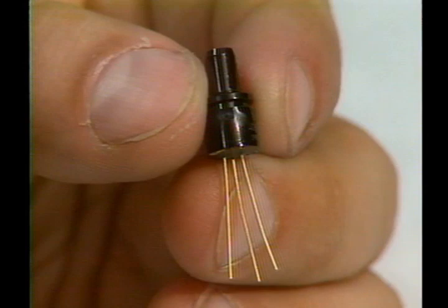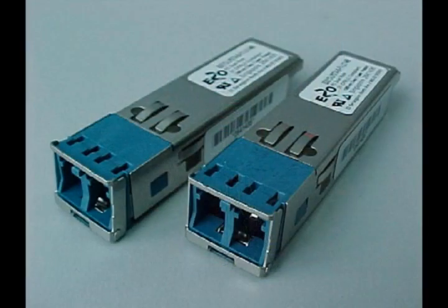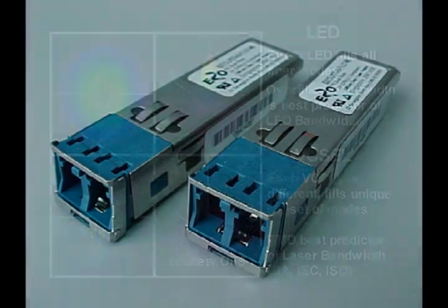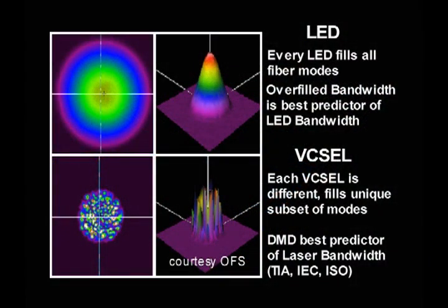The advent of 850 nanometer VCSELs drove two fundamental changes in multimode fiber. The first was with manufacturing performance measurements. For decades, modal dispersion was characterized by overfilled launch bandwidth, a frequency domain measurement of pulse broadening which accurately predicted multimode system performance with LEDs. However, because VCSELs are lasers, they launched a restricted spot size into the core of a multimode fiber, exciting only the fundamental and low-order mode groups.